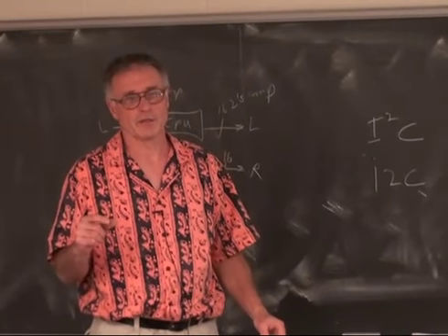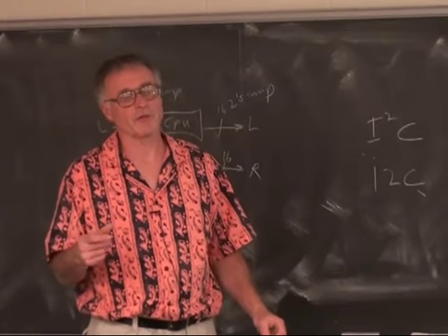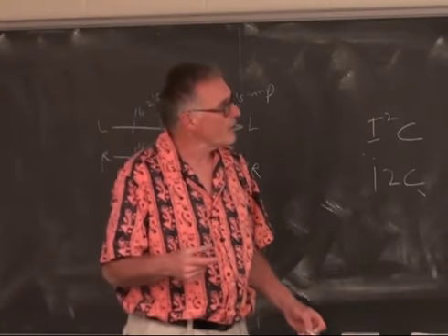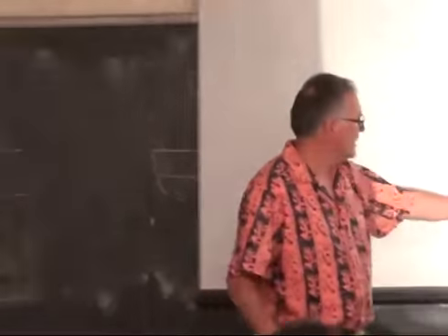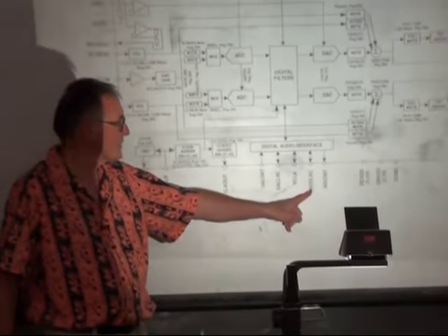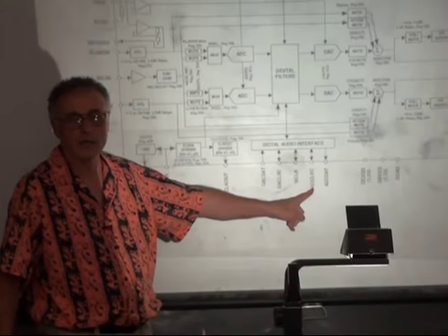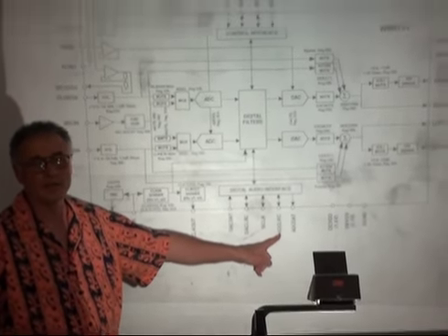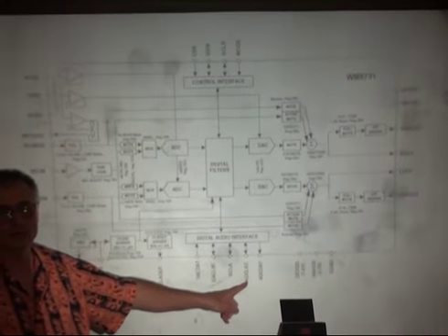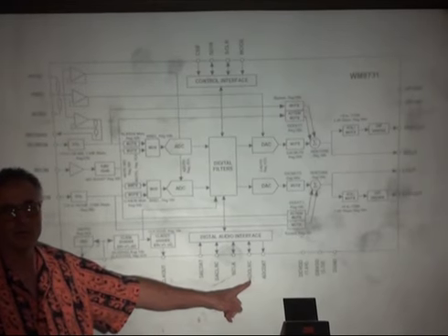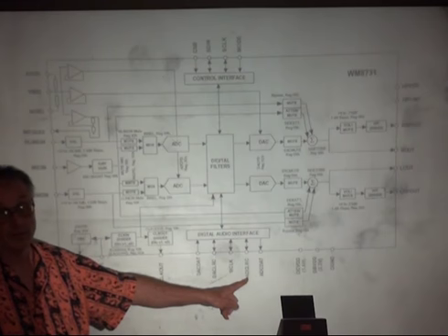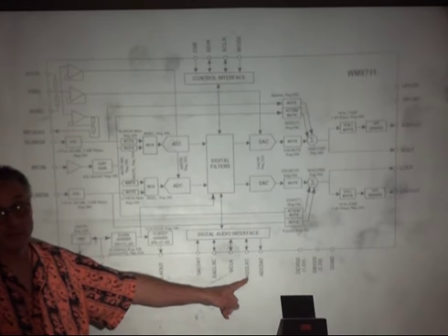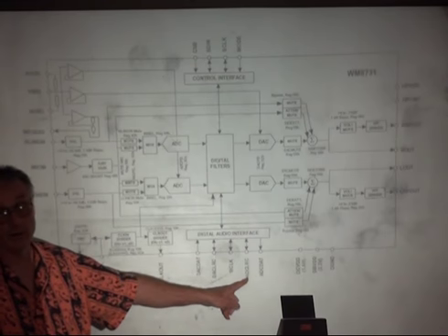Quite often, 5 times a day, quite often you will find when you're using this chip that the bit clock gets out of synchronization with the left-right clock. And so part of the data from the left channel will end up in the right channel, and part of the data from the right channel will end up in the left channel, which makes very ugly waveforms. And the only solution to that is to cycle the power.